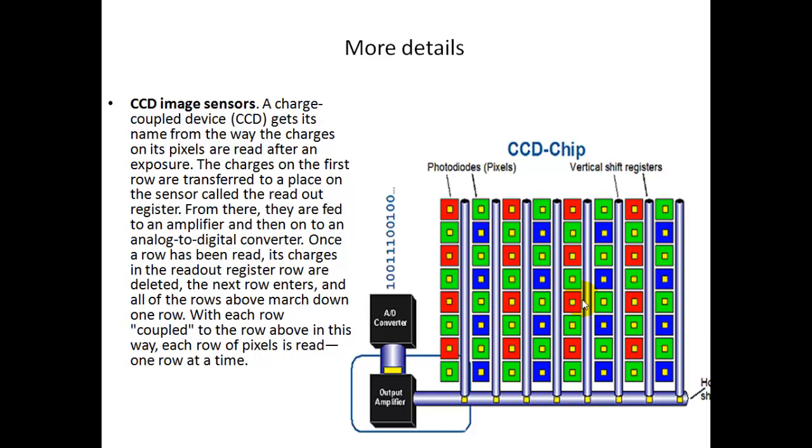Here's another graphic which shows this. This is the CCD. As soon as the picture is taken, all these packets of charge move down to the serial register, and then they move this way, and each packet is read individually, amplified, and turned into a digital signal.